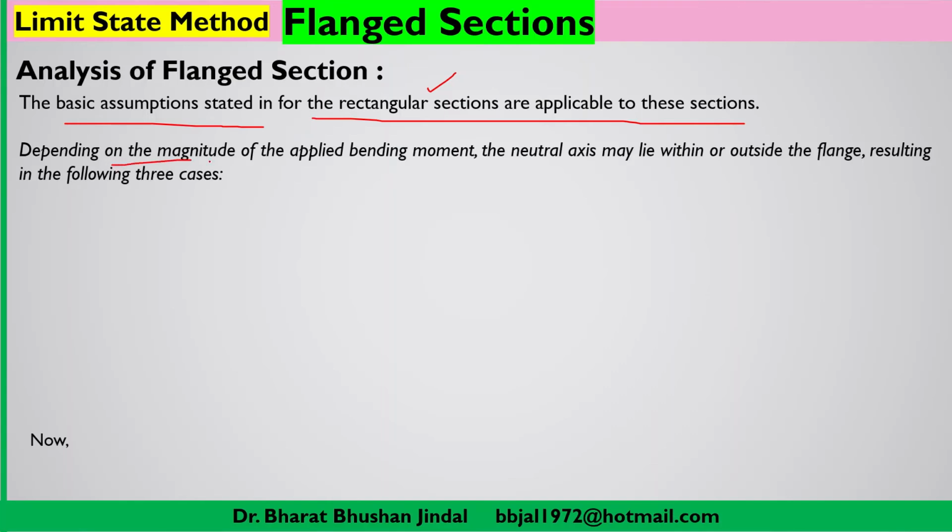So depending upon the magnitude of the applied bending moment, so how much bending moment is coming on the section, accordingly the neutral axis will be shifting, or neutral axis may be below the flange or it may be within the flange. That means you can say neutral axis may lie within the flange or outside the flange. So we have different cases. Accordingly, we have to decide what should be the effect of the applied bending moment.